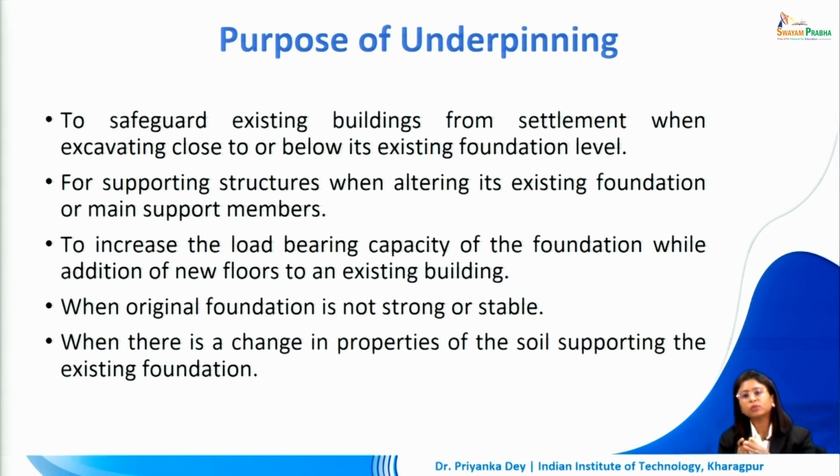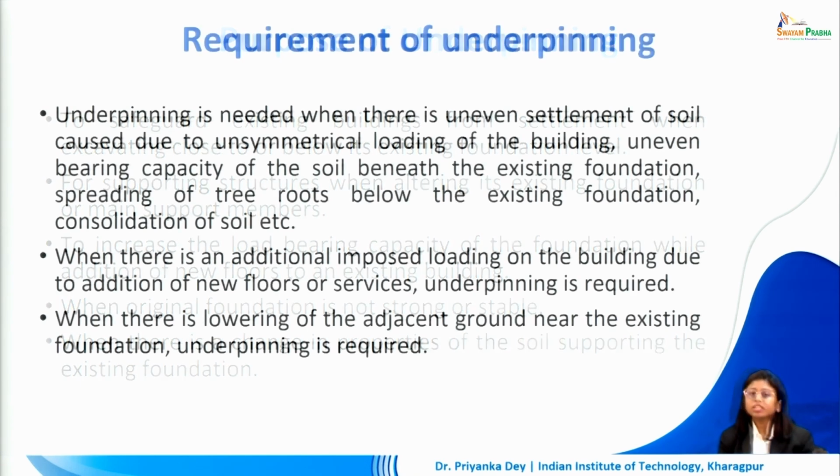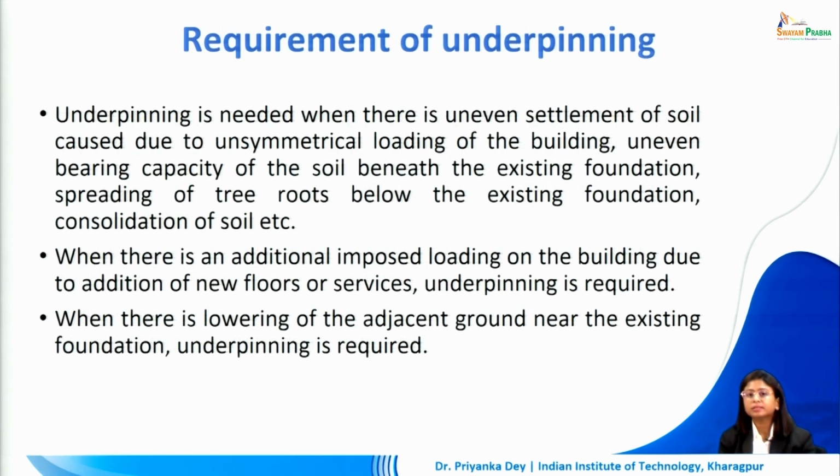So now we cannot destroy the existing building. While protecting it, we have to undergo some amount of transformation in the foundation level. That is where underpinning comes in usage. Underpinning is also needed when there is uneven settlement of soil, which is either caused due to unsymmetric loading of the building, or if there is uneven bearing capacity of the soil beneath the existing foundation.